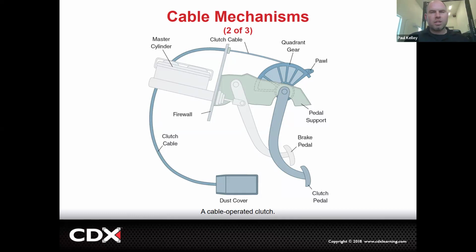It's a little backwards from what you'd expect. So in other words, if you were to have the clutch pedal up, the cable's loose, the fork is going to be basically released from pushing up against the springs. When you push the pedal, you're literally pulling the fork and the release bearing up against those diaphragm springs, for example. Okay. And this is where it gets a little bit tricky with this style, which is why it would not be my recommended design.